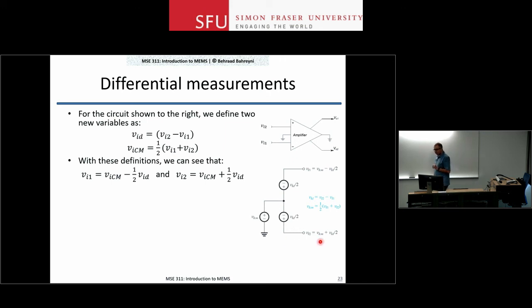For differential amplifiers, I keep everything symmetric in my design, from the input stage where I choose different transistors to build that circuit, all the way to the end. I keep things as symmetric as possible. By doing this, I can quickly show the response of the circuit to the common mode signal, VICM, and the response of the system to the differential signal.